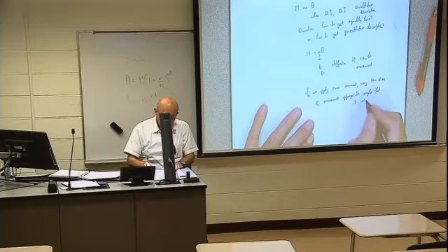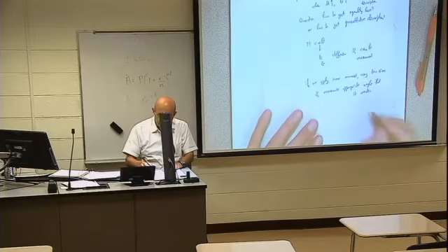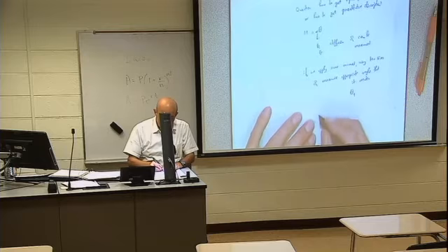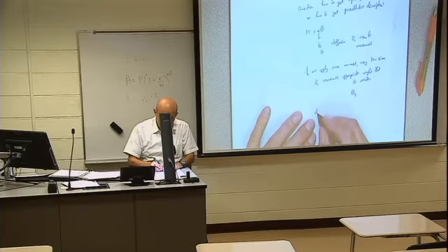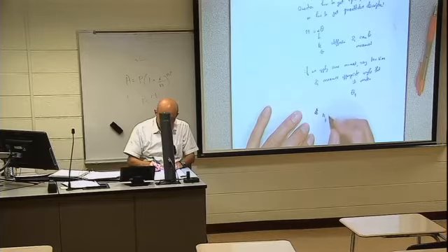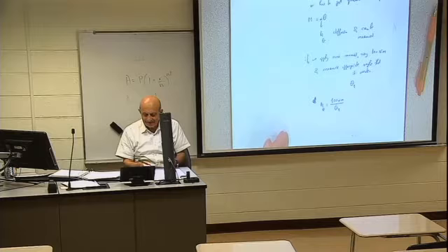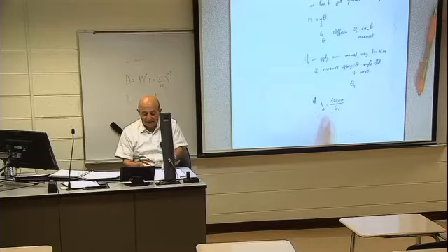Okay, so I will call it theta 1. Then this K theta equals 100 Newton meter divided by theta 1. So that is how we measure the stiffness. Just apply a certain moment, check what angle the system rotated, and the ratio will be this stiffness.